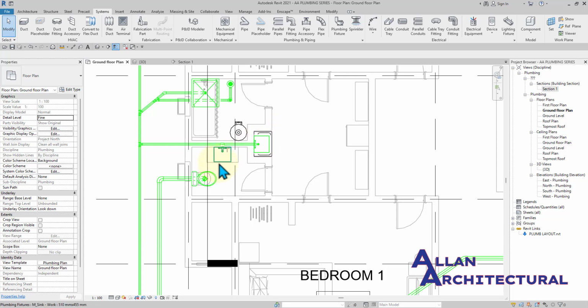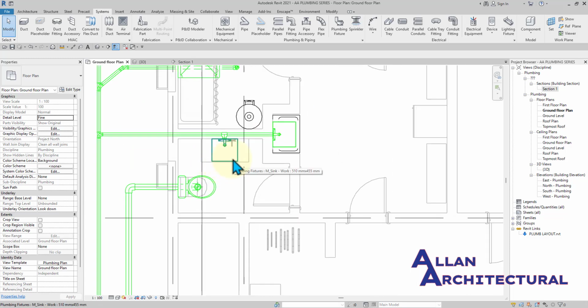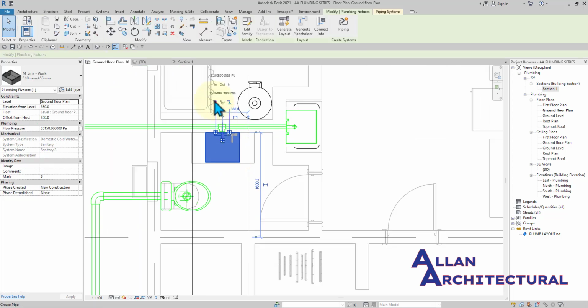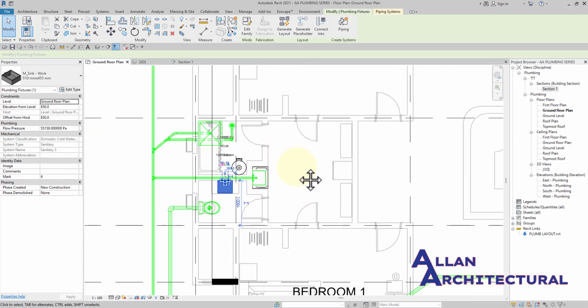So now you guys should also know that Revit can actually generate a layout and connect all of these together for us, which is going to be very fast. Instead of us clicking here, clicking on the water heater, going up and drawing all of them together, Revit can actually create a piping system where it can generate a layout for us.